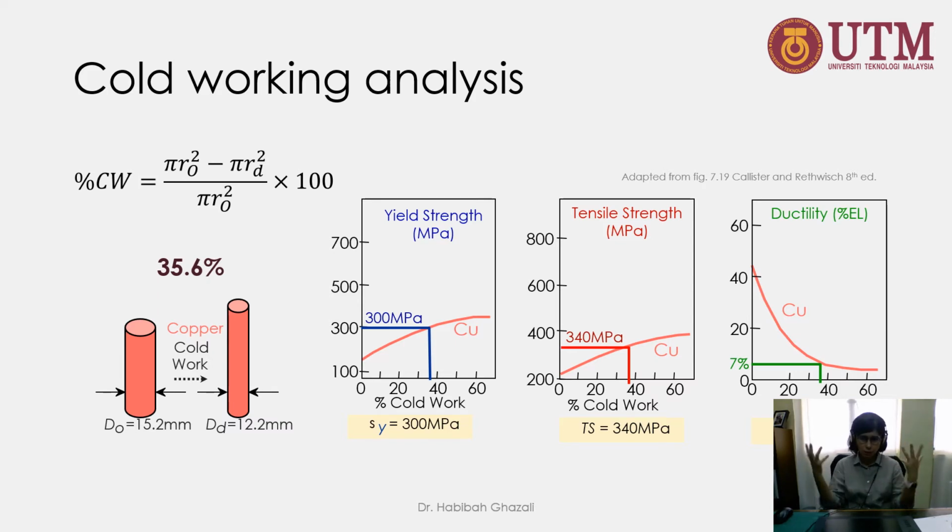It has a huge number of slip planes, where when we activate plastic deformation, the dislocations will slip over this huge number of slip systems. So they are very ductile materials. But as we induce plastic deformation, it will reduce its ductility.